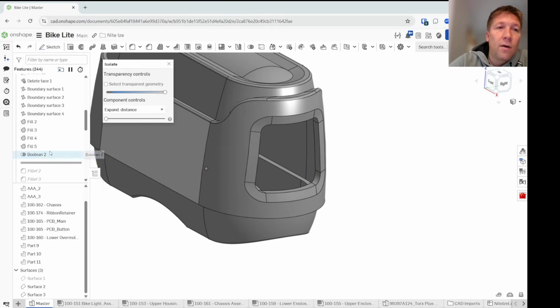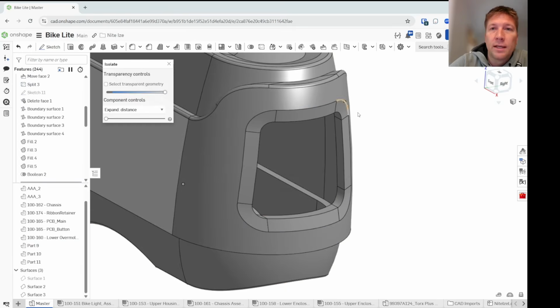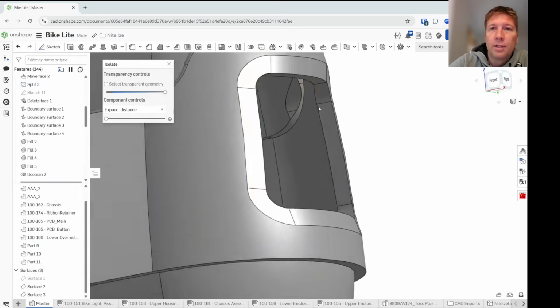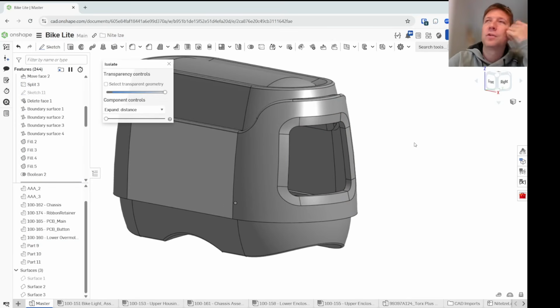All right, so now this Boolean, remember I just built this little body out of surfaces. And now I'm just going to knit that body or consume that body into the other body, and I'm left with a single body. And you might wonder, why didn't you just do a chamfer all the way around the edge right here? Well, the chamfer tool is for really general conditions.